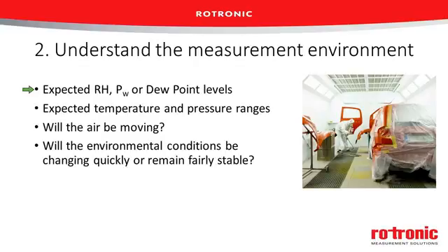If you're in a 500 psi gauge, really high pressure tank, not many instruments can handle that kind of pressure. But if you're in a 100 psi gauge compressed air system, there are more instruments that can handle that, but still some don't. So know your environment.